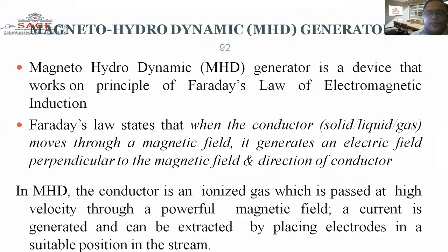Another topic is the MHD, short form of magnetohydrodynamic generator. That is a device that works on the principle of Faraday's law of electromagnetic induction. Faraday's law is already studied in earlier classes. Faraday's law states that when a conductor, which may be a solid, liquid, or gas depending on the application, moves through a magnetic field, it generates an electric field perpendicular to the magnetic field and the direction of the conductor.